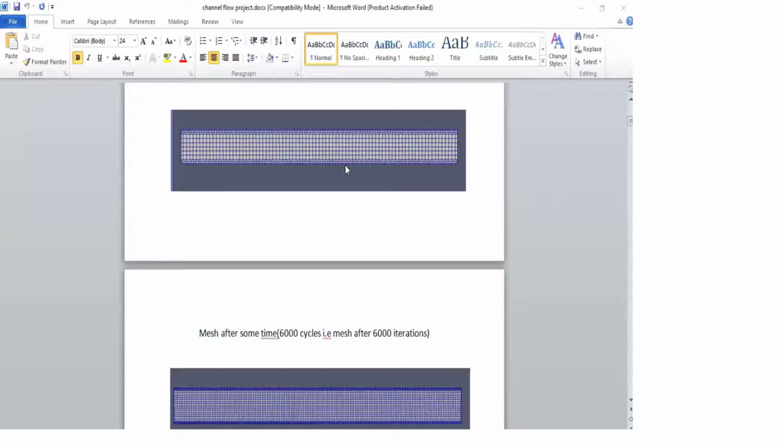Understand that. If there are 5 blocks which are seen here, the Navier-Stokes equation will be solved 5 times. If there are 100 blocks, for 100 times Navier-Stokes equation will be solved. If there are 2000 blocks, it has to solve for 2000 blocks. So it is affecting your computational time, and it will also directly impact your memory, because the more cells, the more calculation. It will require more space, more RAM.